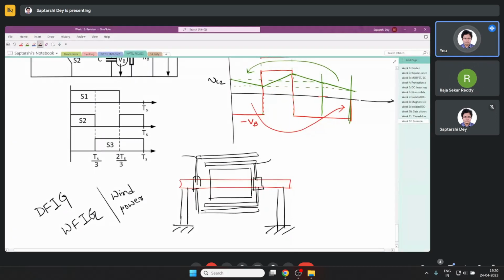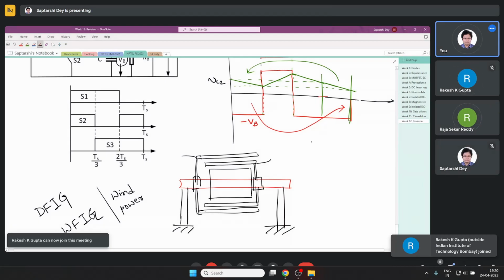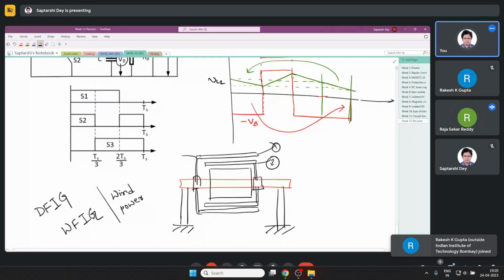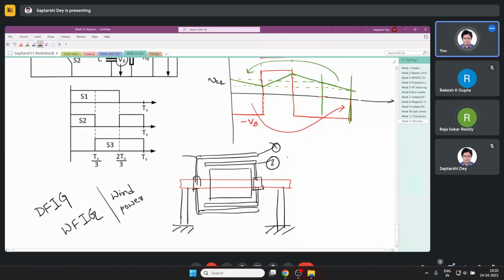And if you look at multi-port, one example I know of is, say, between these two rotors, say rotor 1 and rotor 2, you can have a gearing action in between them, electrical or magnetic gearing action, and you will get two outputs, means outputs at different speed and torque levels.